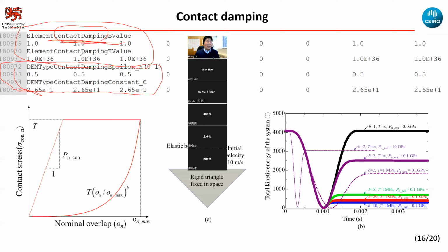For the uniaxial compressive test with the plate and the rock, we can ignore the contact damping. It's unnecessary to use it. In the control parameter, you can control whether it is used. If you do an analysis of a body impact, you need to use it.